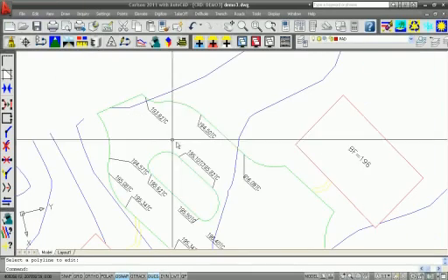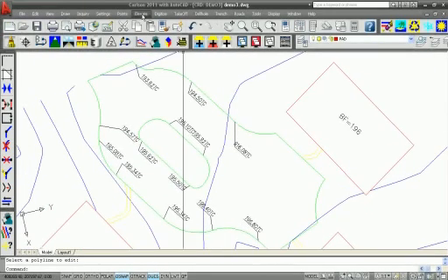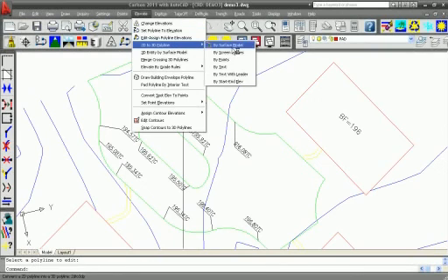We also want to use these labels on here. In older versions of the software, if I were to run by text with leader, it would override our elevations that we just set by the contour line. Now, what's new with 2011, this will add the elevations to that existing line, and they'll be locked in like that other command. They'll be control points. So by text with leader,